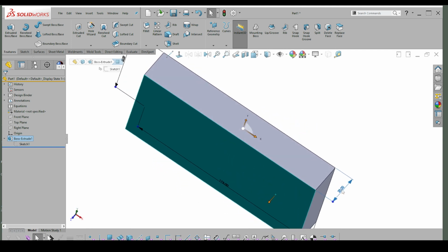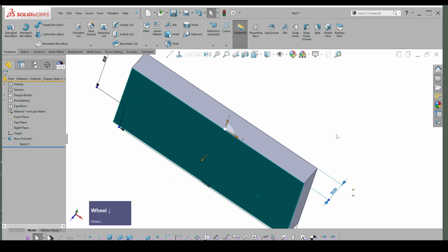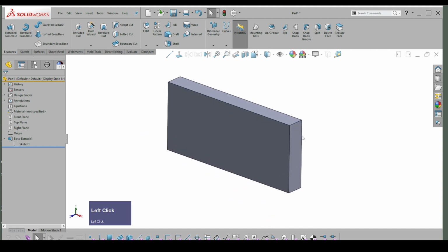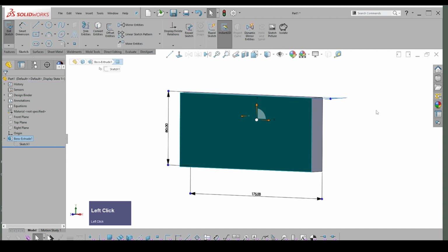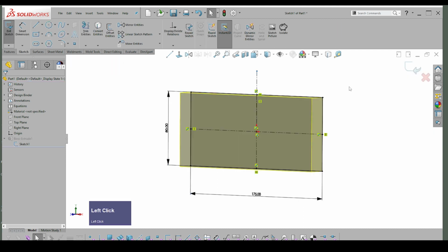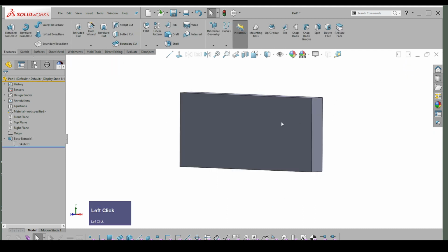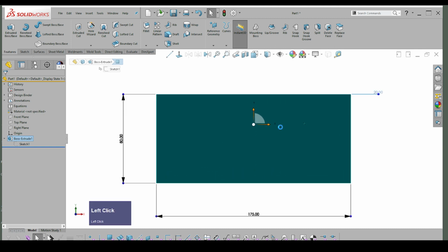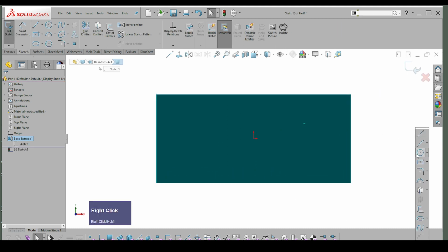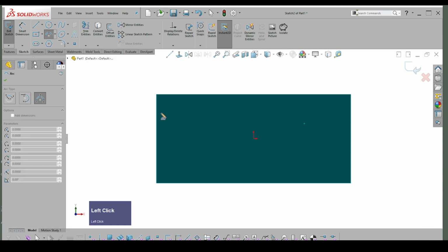Here is the thickness. It's 30. So you can always click on that and do a very quick parametric change to this item, this handle. I'm going to put in a sketch on the front face. Oh, okay, there, I edited a sketch. So just be careful of which button you select. Edit sketch is at the top, sketch is underneath it, and I'm going to put in a 3-point curve.